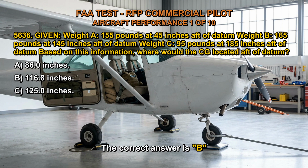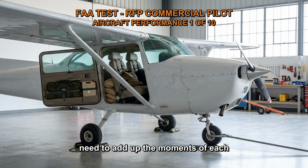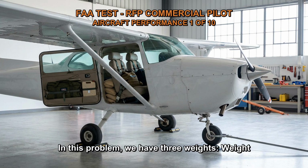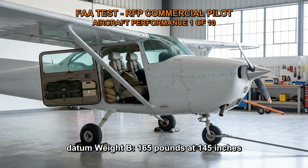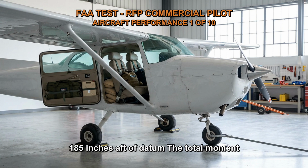The correct answer is B. To calculate the center of gravity, CG, we need to add up the moments of each weight and divide by the total weight. The moment of a weight is calculated by multiplying the weight by its distance from the datum. In this problem, we have three weights: weight A, 155 pounds at 45 inches aft of datum; weight B, 165 pounds at 145 inches aft of datum; weight C, 95 pounds at 185 inches aft of datum.